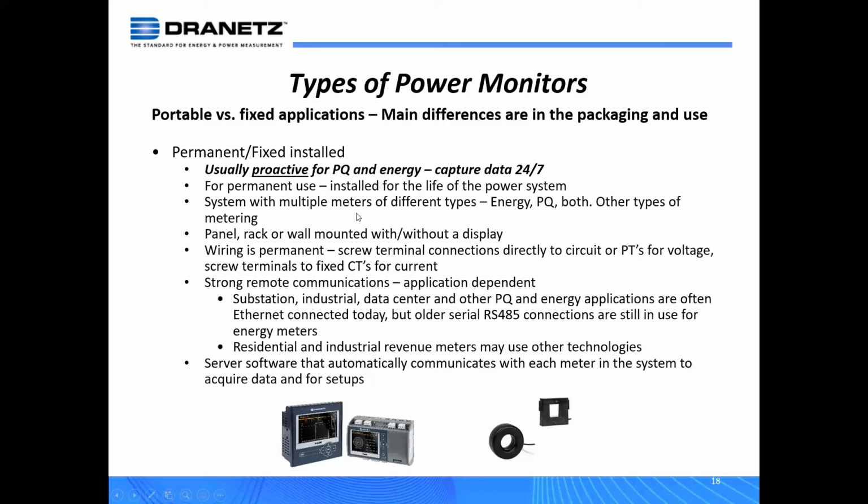There's different types of meters, from energy to PQ to both, and other types of metering. There's different ways in which you would mount it, from panel mount to rack mount to wall mount, with or without displays. Since wiring is permanent, screw terminals are the most common for voltage leads, as opposed to clip-on connectors. Strong communications is essential.